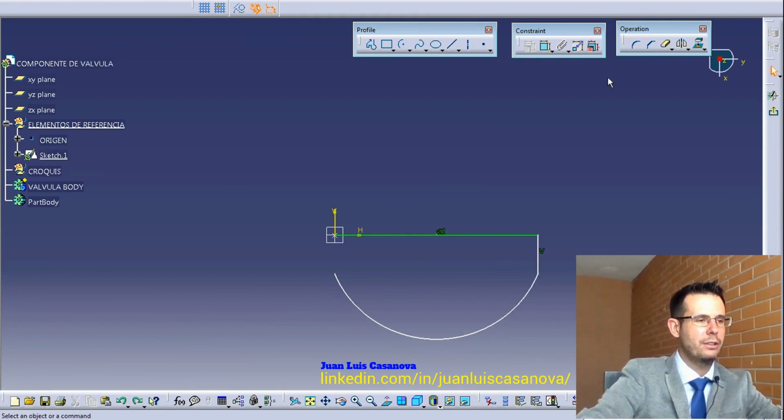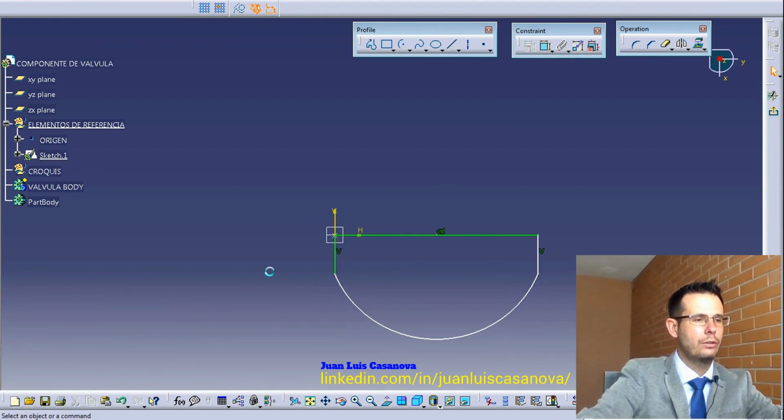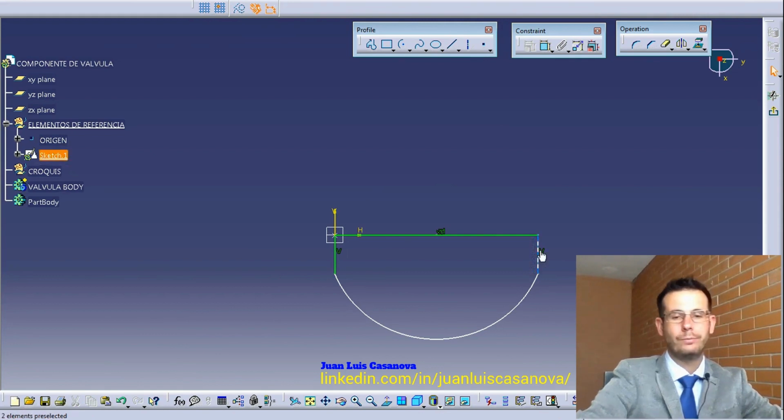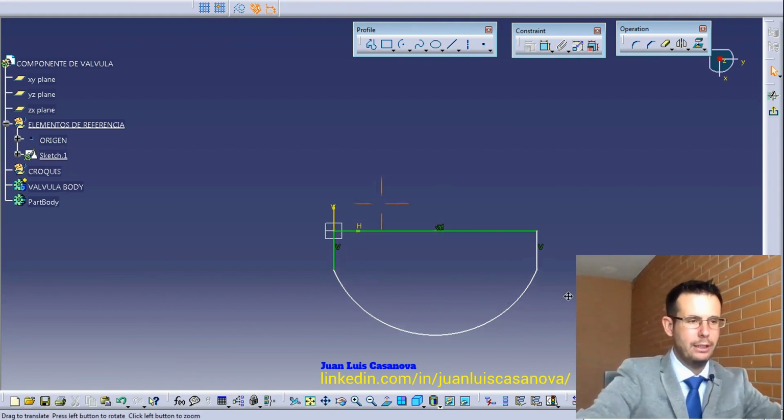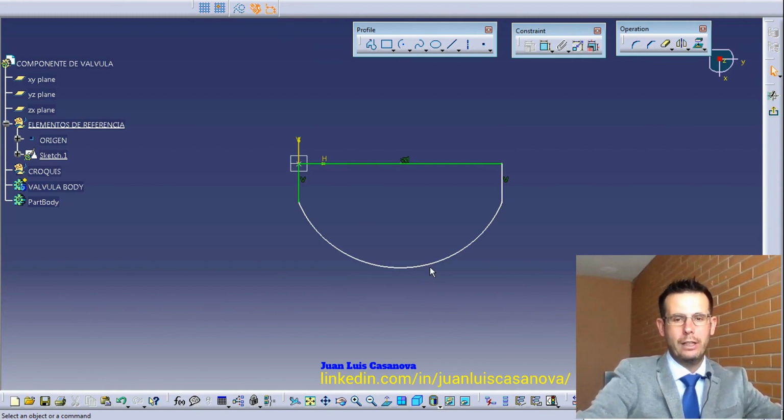Now we are interested in dimensioning. Now we are going to dimension. We always have to take into account two things, dimension and position. So we are going to dimension first, in size, then position. We are going to select this as the dimension icon. This is constraints. Yes, it can be translated as dimension, and it asks us for the dimension element. We start with the radius.